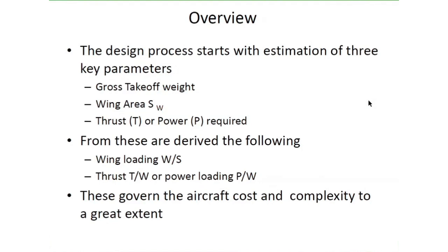So if you have seen most of the passenger aircraft, their engines are massive and extremely high bypass, sometimes even 10 or 11 bypass ratios, and they are very fuel efficient, almost as good in terms of fuel consumption as the old propeller and piston engine aircraft. Whereas in combat aircraft, we cannot afford to put such big diameter engines, because the diameter increases with the bypass ratio. You cannot have 9 to 10 bypass ratios in a combat airplane because there the engines are housed inside the fuselage. So all said and done, some of the modern combat airplanes do have a bypass engine, but the bypass ratio is 0.5 or 0.6 or something like that.